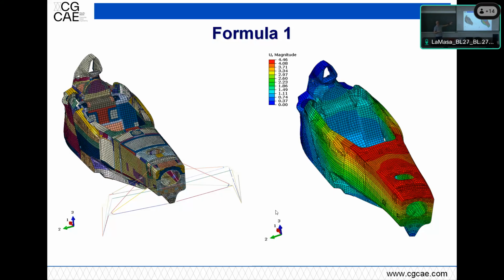Computational power was what it was. There was no parallelism, so it was one CPU. They were starting in those days to have Nastran for more CPUs. And in our days, this thing is made easier. The ply-based approach is used. So you just define your sets where you want to apply the ply, exactly as if you would do in production. You have your mold, and you place your ply where it has to be. And then it's the software that converts this information into the ply-based model.